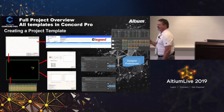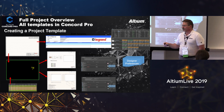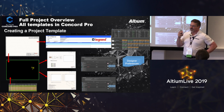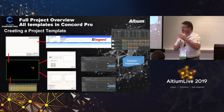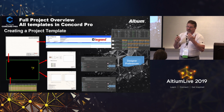The point is that you want to set up various design rules. And what you should do is go in and set up an entire library of design rules for specific design types. That's what we ended up doing. We have our high speed, we have our high power, because we're not just digital high speed designers. We actually have a combination. We actually have very high power.